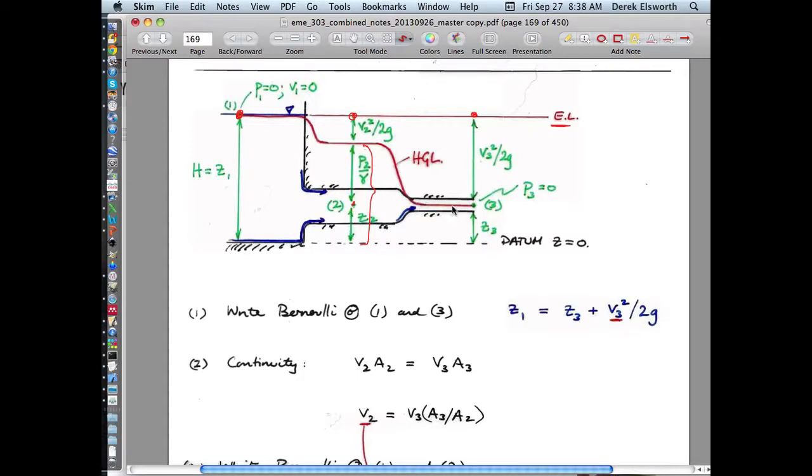And as you constrict it even further, then the velocity that you have in this particular case, you know that at this exit point, the fluid pressure has to be 0, right? It's coming out, all of a sudden it sees air pressure rather, so the pressure here has to be 0. So de facto, the elevation can only be the elevation, and so the remaining portion of it has to be further accelerated to be a larger velocity. And of course you'd expect that from continuity because the area here is large compared to this area. The flow rate Q2, if you like, has to equal Q1.